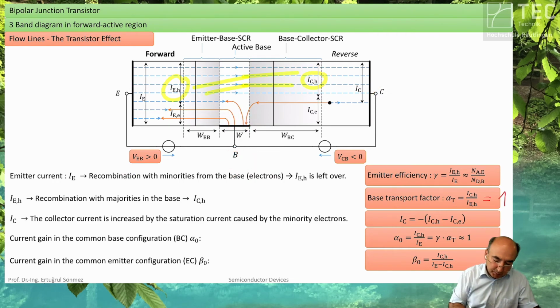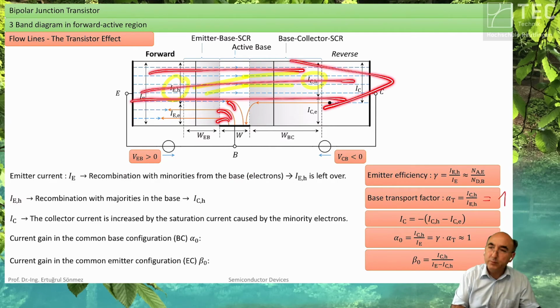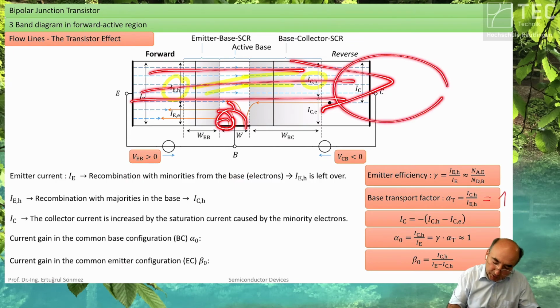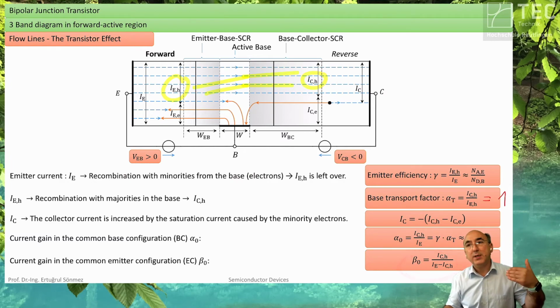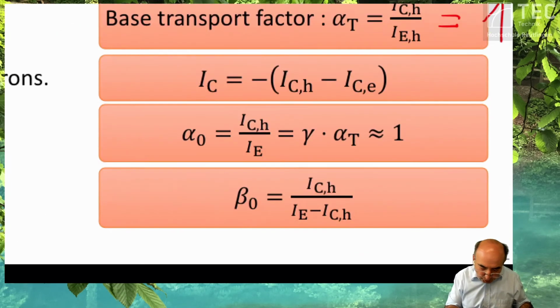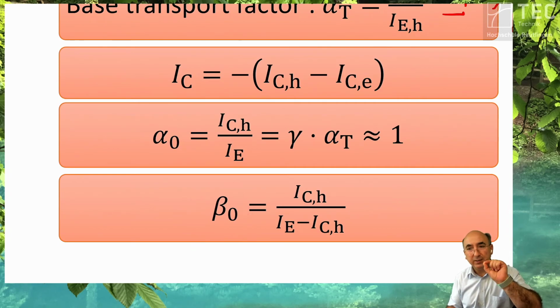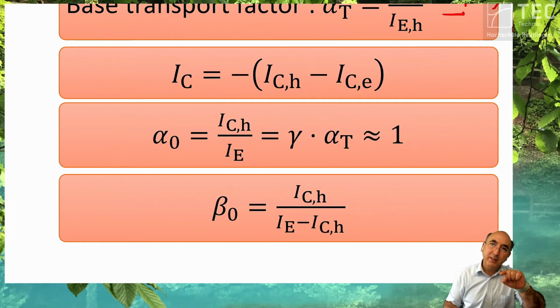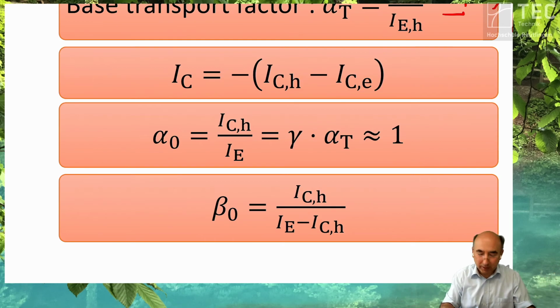And this base current produces a collector current. So a small base current produces a large collector current. And this is calculated by this equation. It's the current amplification. Don't be confused. It's also called beta. It has the same variable like the transconductance parameter in the MOSFET. But here it does mean the current gain. Sorry about that. It has happened to be equal.